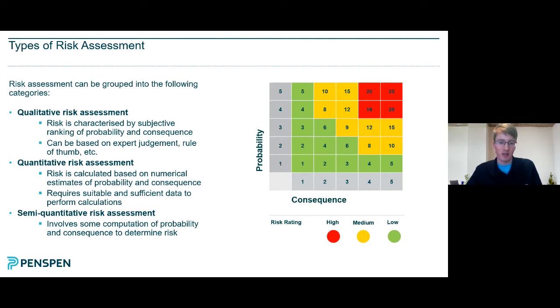Data management is fundamental to integrity management as a whole, and risk assessment as well. Thinking back to the San Bruno incident that I shared earlier, data management was found to be quite a significant contributing factor to the failure, whereby the operator had very poor records, and that contributed to them not fully understanding the risks posed to their pipelines and resulted in a failure.